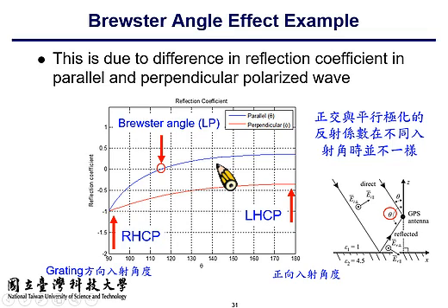the Earth's material, so that epsilon is 4.5, and the reflection coefficient behaves differently for perpendicular and parallel polarization. For perpendicular polarization, the reflection coefficient is negative for all incident angles, from -1 to about -0.4.